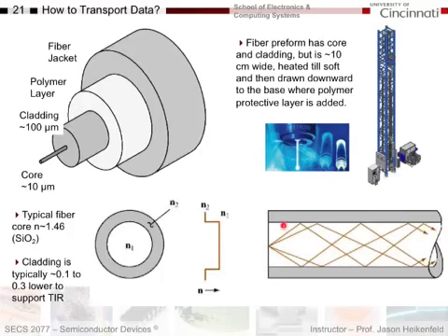And just like those dielectric mirrors we had before, the beauty of this is there's no optical loss. If I used a metal here, I'd have some optical loss, right? So by using dielectric materials, in this case silicon dioxide, with a little bit higher refractive index in the middle, lower on the outside, I get total internal reflection, which has no optical loss whatsoever and allows efficient data transmission.